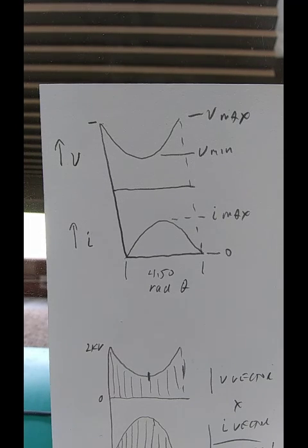The maximum voltage is power supply voltage, assumed to be 2 kV. V minimum, in this case, I've changed to a different operating line because I realized the one I had chosen, which ranged from 2 kV down to 350 volts, would have generated 2.45 kW. That's not legal in the US and amateur radio. So I took a much lower operating line, which ranges from 2 kV max down to 1 kV and a maximum current of 200 mils. And that tube is just loafing along, so it'll last forever. It'll still produce roughly a kW PEP, and that ought to be enough, especially as band conditions improve.